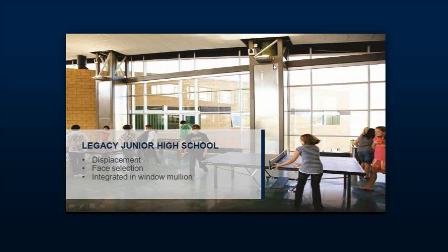So I look at this example, and I look at this previous example. How do you possibly use overhead air distribution inside these types of structures? It's a challenge that I would find quite invigorating and also enough to make me beat my head on the wall, perhaps. This one in particular, there was a design project competition that I was talking to the instructor on, and he said he had 3 or 4 teams that looked at how to condition the space, and they all tried to put overhead diffusers in, and none of them considered displacement.